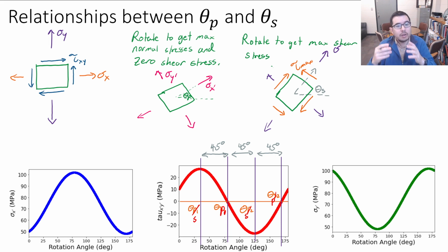What did we say? We said that it's because brittle materials fail with normal stresses, okay? In this portion, we focus more on looking at maximum shear stresses. Turns out the ductile materials fail more frequently in shear.